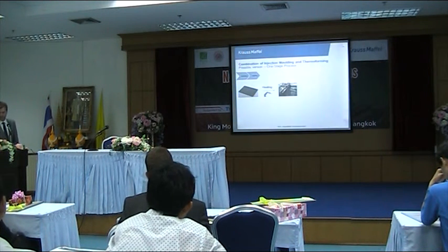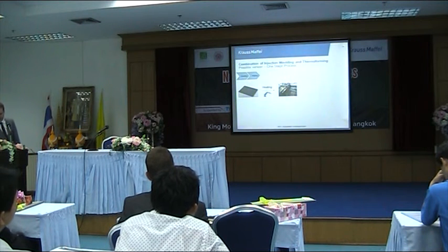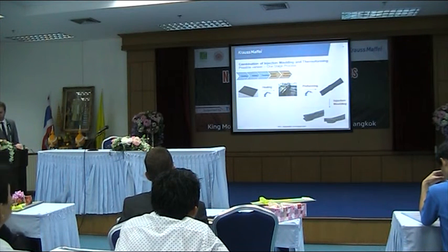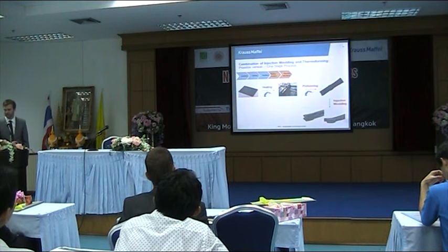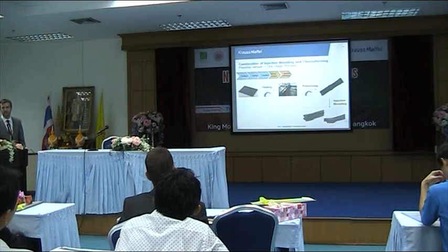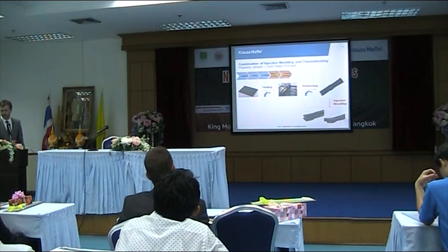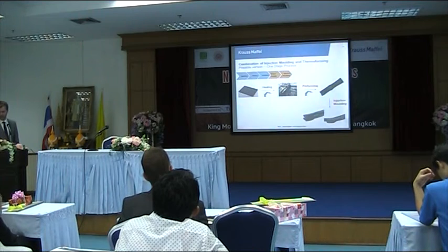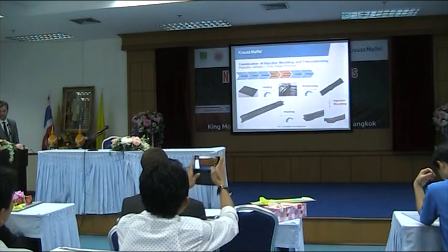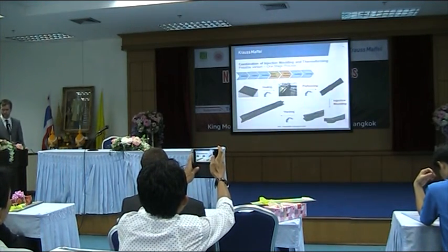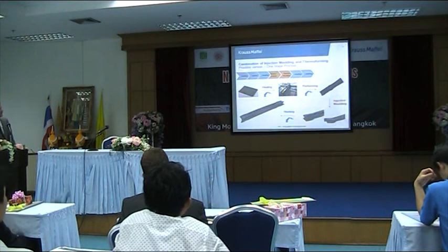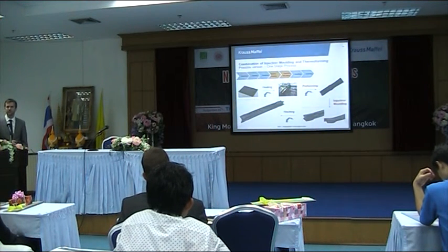And now we have a one-stage process. So again, you have the organic sheet. You will heat it up. You will preform it inside the mold. The mold now needs to get more complex, and I think a lot of industrial know-how is in this forming inside the mold, but you can directly aftermold it, and you will have the finished part, and you will skip several steps. So this is the finished part, and it's a test part to substitute metal.